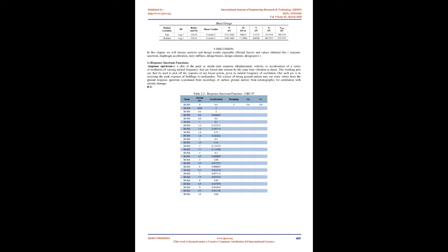The scope behind presenting this project is to learn the relevant Indian standard codes used for design of various building elements such as beam, column, slab, foundation and staircase using the software ETABS, under the seismic load and wind load acting on the structure, to find out the values in the project: base shear, time period, maximum story displacement.